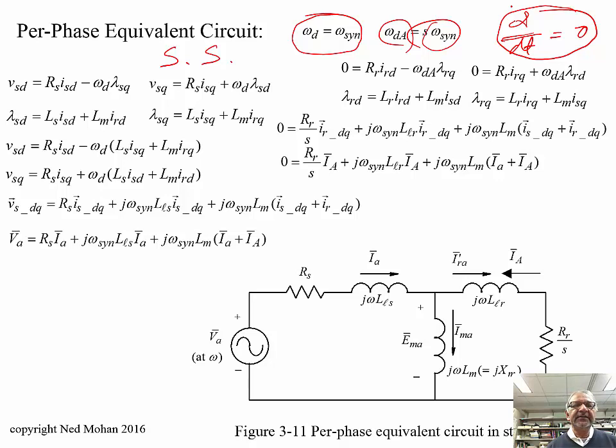So what we do is write equations for all the voltage equations for all the 4 windings we have. That's the beauty of this DQ analysis: previously we had 6 windings which were coupled in the ABC reference frame, and their mutual inductances were dependent upon the rotor position.